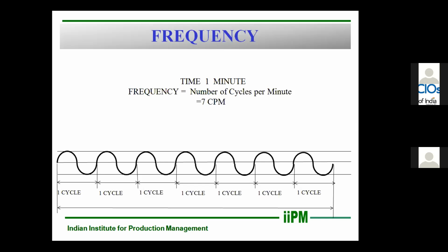Right, sir. You have given an exact indication. We need to know these parameters, because we are finally getting the data online or offline, and we need to know what these instruments are measuring or what they are capable of. Mostly when we generate a graph, or get the time domain, the x-axis will be frequency and the y-axis will be amplitude. Amplitude can be velocity, displacement or acceleration, depending upon the application.